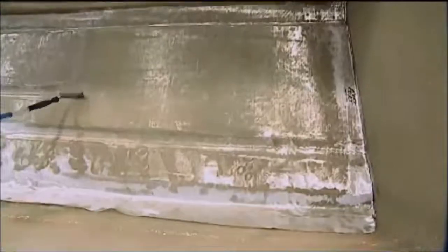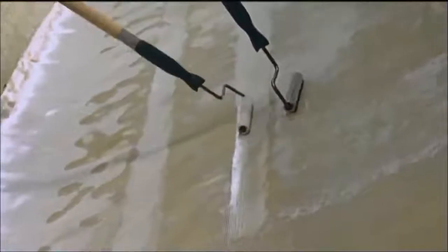The sprayed fibre and resin material is compacted using a roller to consolidate the mixture and to create an even and smooth laminate surface. This also ensures that the laminate properly adheres with the gel coat surface and removes any air in the resin matrix. The whole laminate is allowed to cure at room temperature, after which the part is then demoulded and sent for finishing work.